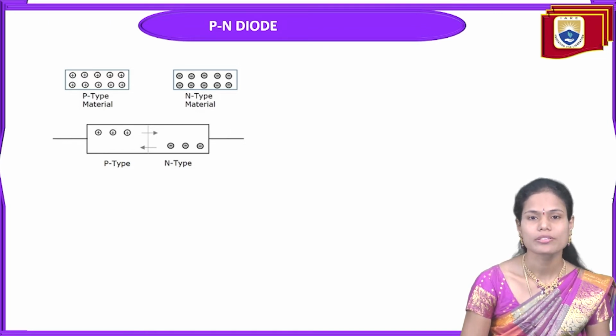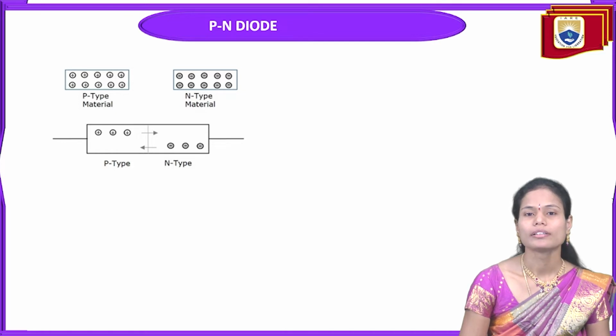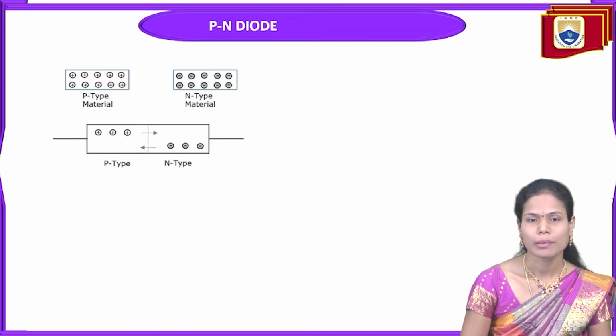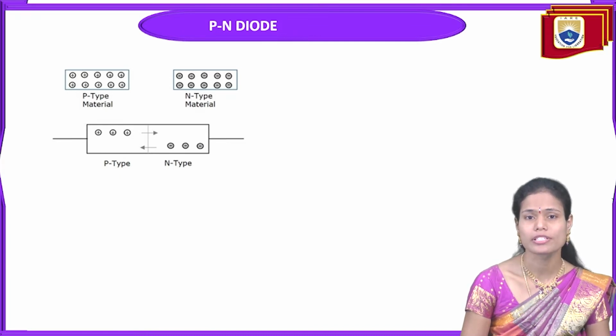Here we are saying that these capacitances exist in the operation of the PN junction diode. The transition capacitance will exist in the reverse biased PN junction diode, and the diffusion capacitance will exist in the forward biased diode. Before going to these capacitances, first we have to know the actual operation performed in the case of a forward biased as well as reverse biased PN junction diode.